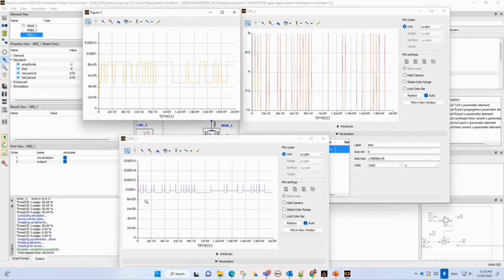You see here, and this is why there is saturation, because if you remember, we have a linear region. If we plot the transmission versus wavelength, the best bias point is the middle of our linear region. If we go to a higher voltage, our AC signal is saturated. So this is the whole story.